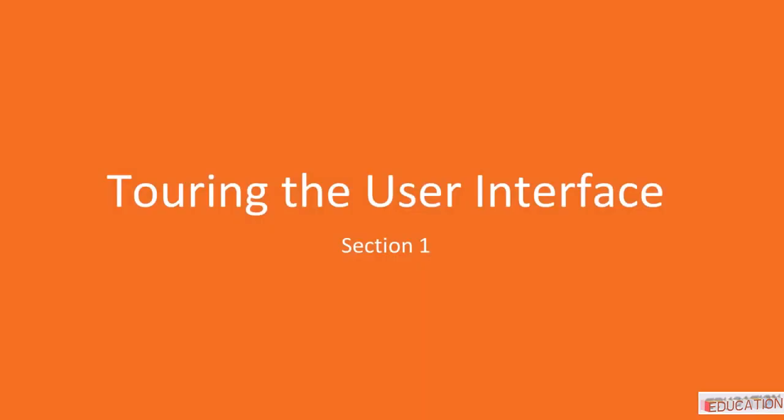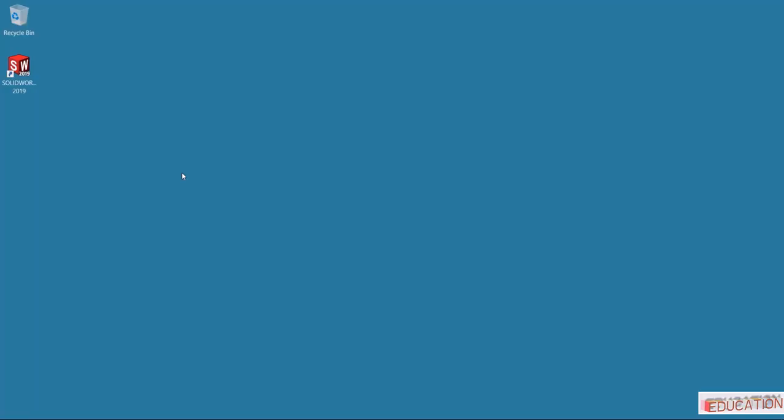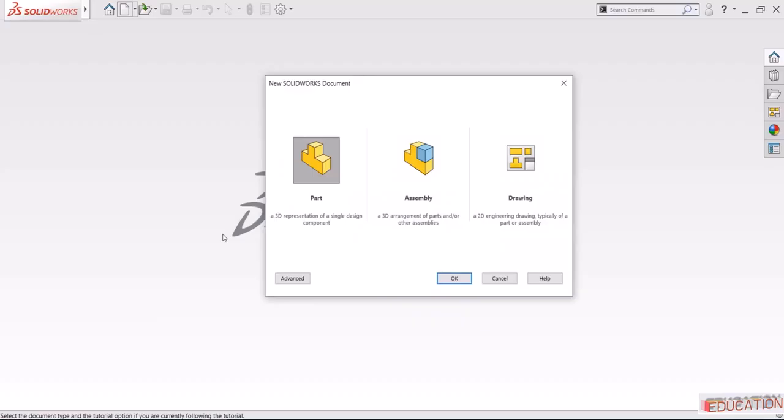Hello everybody and welcome to section 1. Before we go deep in SolidWorks, we will learn how to launch the software, how to create a new file, and we will tour the interface. To launch SolidWorks, double-click this icon. As you can see, we have 3 main options here: part, assembly, and drawing. Later on in this course, we will talk about each one in detail. For now, we will start with part.